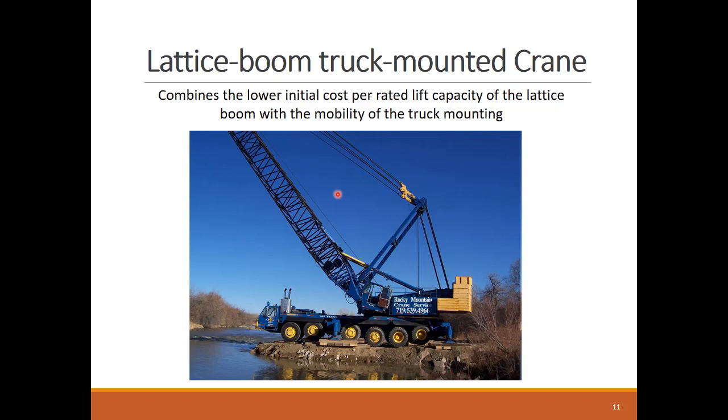Lattice boom truck cranes are ideal for steel erection, port and bridge work, and are known for quick line speeds. The lattice boom takes a long time for assembly and setup, but their lightweight, efficient truss lattice design makes them more affordable than the telescoping boom for the same load.